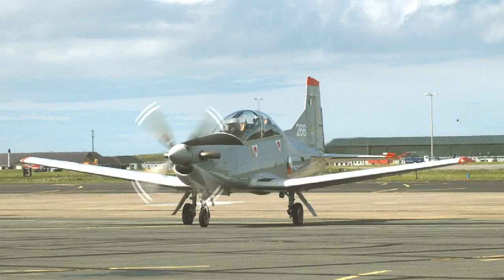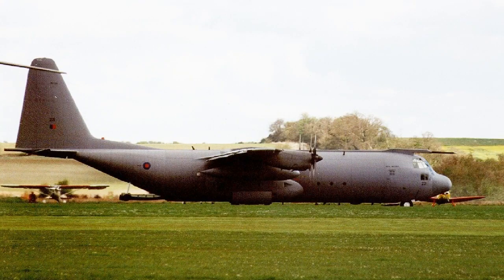The free power turbine has further advantages. The propeller of a free power turbine engine can be held at low RPM during taxiing, thereby reducing noise pollution and wear on the brakes. A free power turbine engine requires less starting torque than does an engine where the turbines and compressors are coupled together. A rotor parking brake can be fitted to an engine with a free power turbine. This eliminates the dangers inherent in having propellers rotating in windy conditions on the ground.